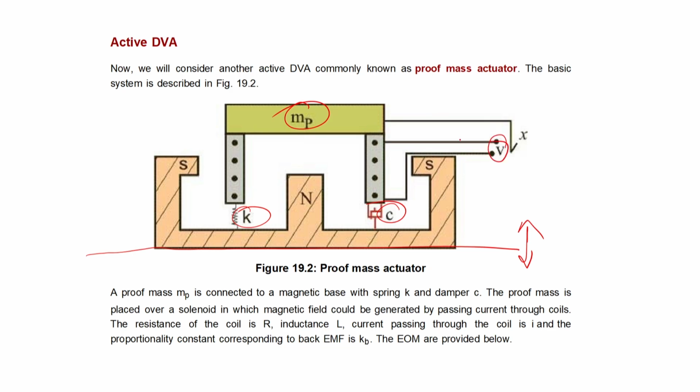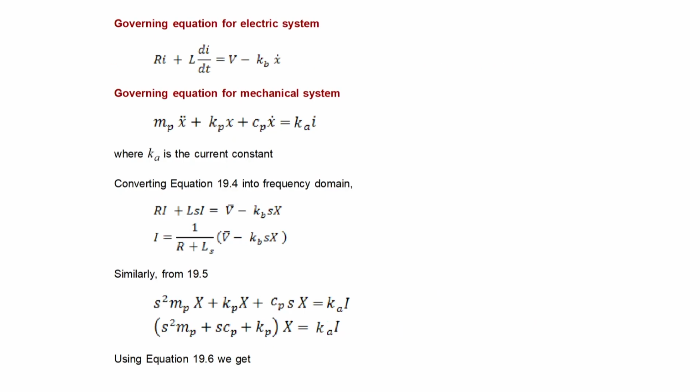By applying the voltage and controlling the polarity, you can create either a north or south pole, in a manner that the mass can either get attracted towards or repelled from the system. So, you can actually generate a vibration in this system. If this force vibration and the original vibration are in opposite phase, they can basically control each other.